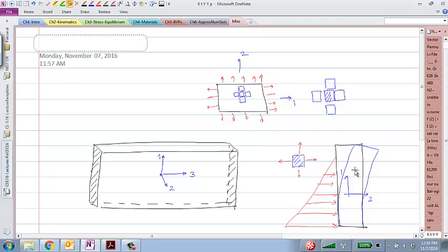The through thickness changes here are typically possible, right? It is moving in the 2 direction. For it to be a plane strain problem in the 1, 3 plane, there cannot be any movement in the 2 direction. Do you agree? But clearly, there is movement in the 2 direction. So you cannot have that as a plane strain. Okay.